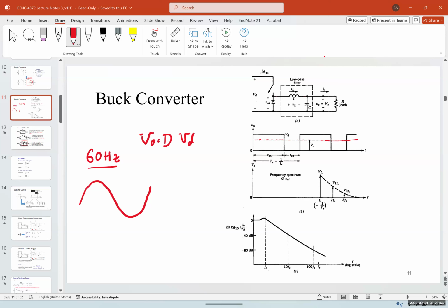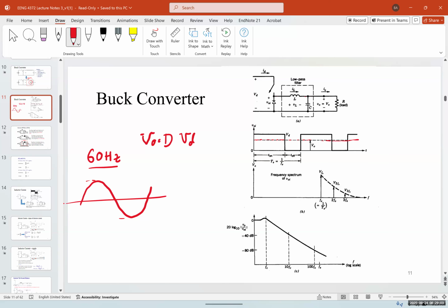The important thing is just the frequency here. Or let's say it's 120 volts and 60 hertz to make it easier. If I want to draw the frequency spectrum, if I do what we call an FFT or fast Fourier transform, we're going to have a peak at 60 hertz. Meaning our signal has a frequency mainly at 60 hertz.